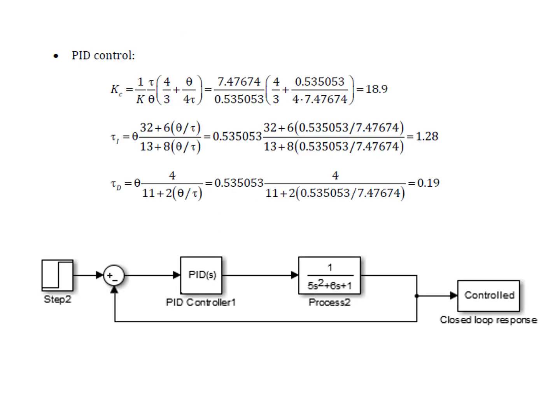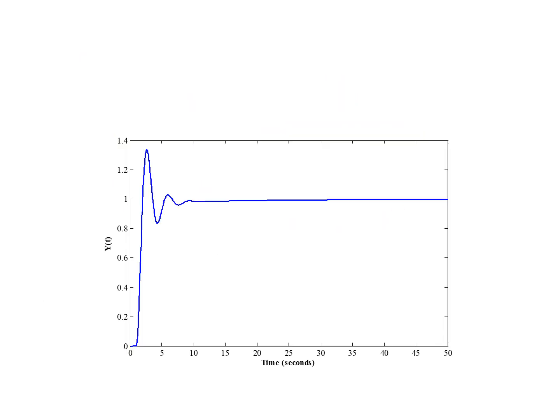Okay. Then our controller is PID controller. So we have to calculate KC value, tau value, and tau D value, and then use here. This is in MATLAB. In MATLAB, you have KP and the KI. So convert this to this, then KD equal to TD1. So substitute and get the response. So that response is like this. So this is the control.